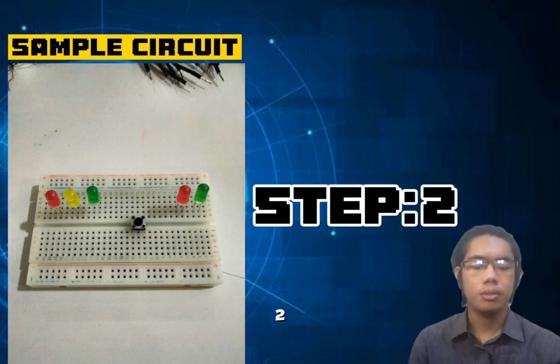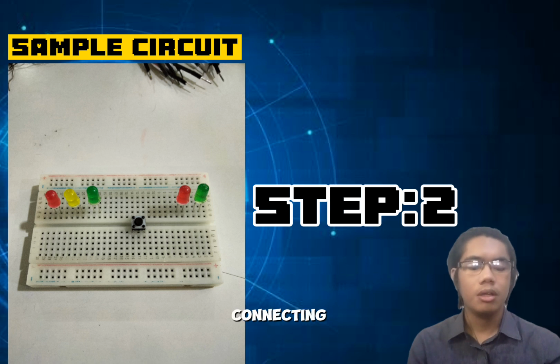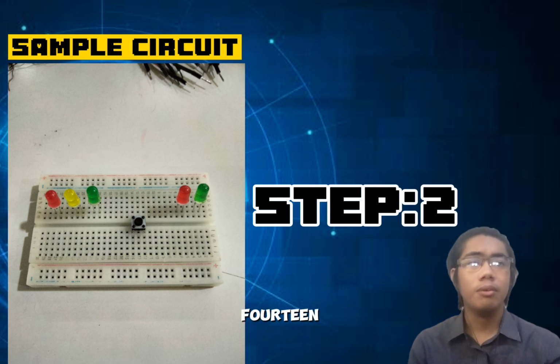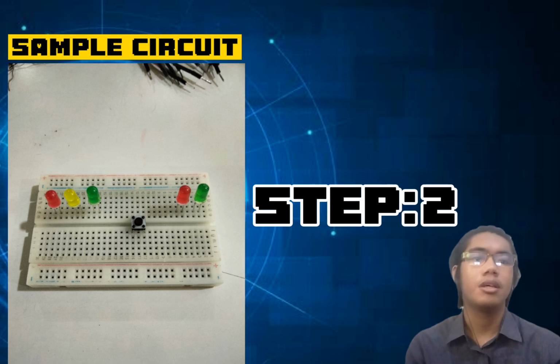Step 2. Place the push button on the breadboard. Place the push button across the breadboard, connecting E12 to E14 on one side and F12 to F14 on the other side.